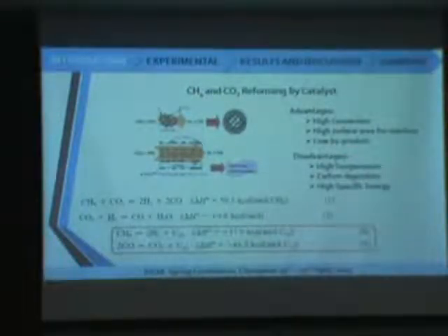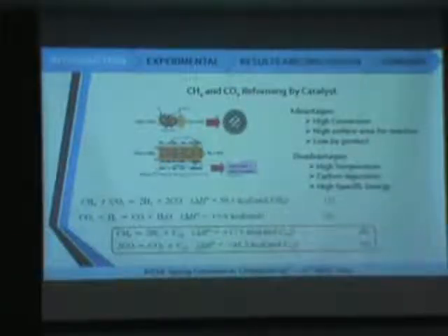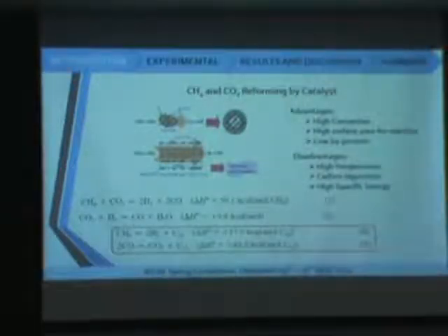By this process, we have high conversion, high surface area of reaction, and low byproduct. But we need to use a very high temperature, and the catalysts are deactivated by carbon deposit, and in this process we use a high specific energy.